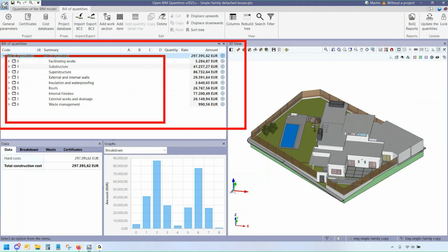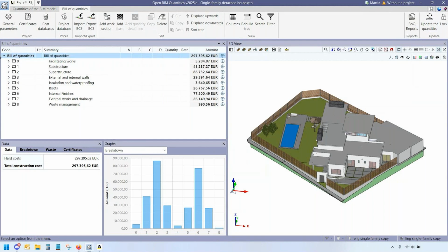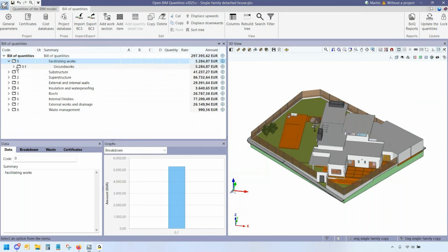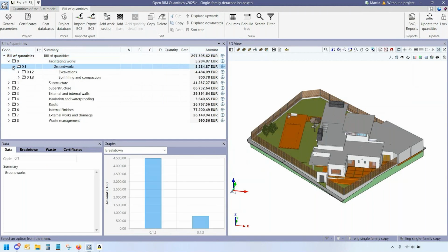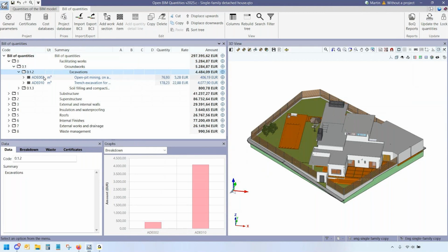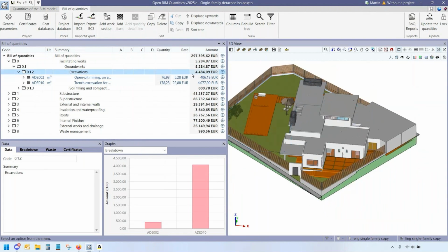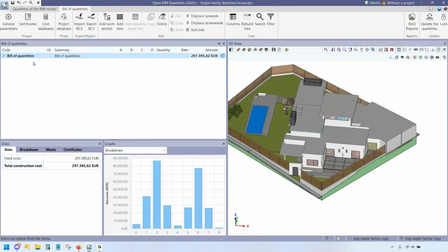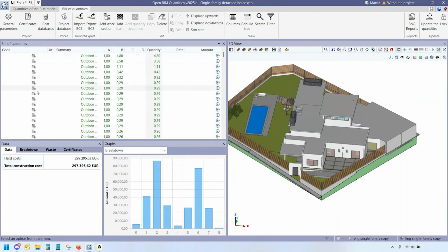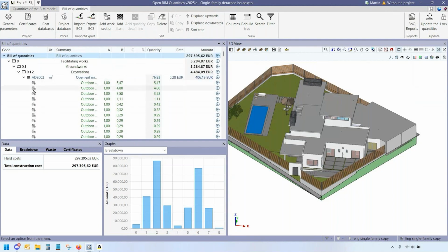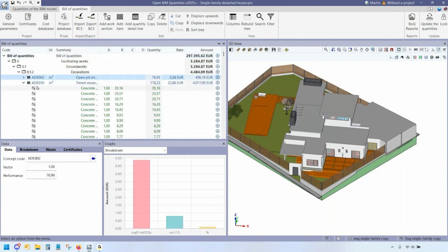I haven't been typing all these. The program reads automatically the price, the code, description, units, and price per unit. And with the quantities that are present in the model, we are automatically pricing the whole project. And we may display the whole thing with a specific measurement displayed, or we could actually group them, get the information in whatever format we need.